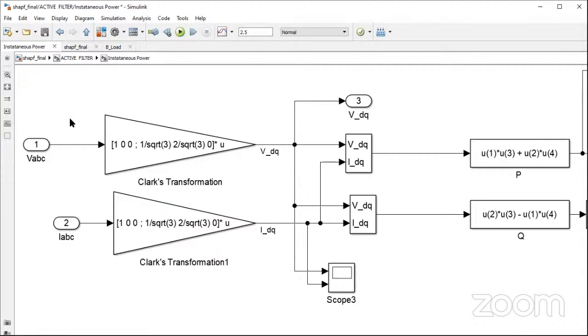By applying the rotating or synchronous reference frame, for the three-phase inverter, here we are using the 120-degree conduction mode inverter only, a voltage source converter. In that 120-degree conduction mode inverter, the A, B, C phases are maintained 120 degrees apart, right? So then you can see here.